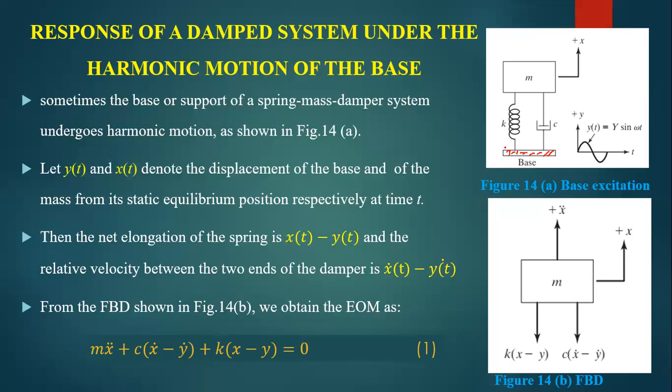And this vibration will transmit to the structure here, or the mass. The mass has an acceleration like this, and the stiffness, the elastic nature of the structure, is K. So we have a relative motion between the two, the relative motion between the foundation and the structure, or the base and the structure. That relative motion is equal to x minus y.